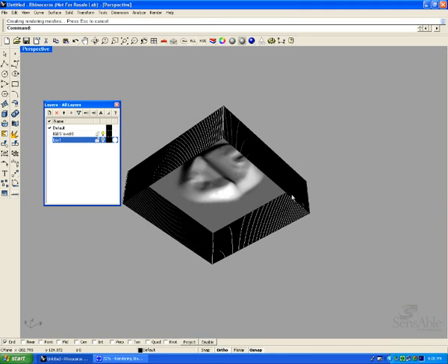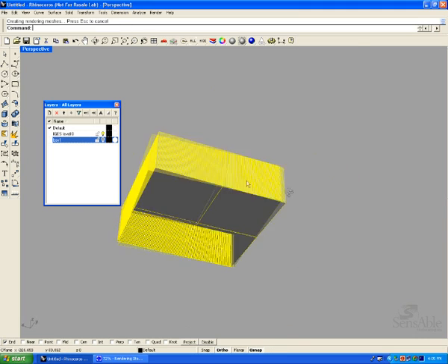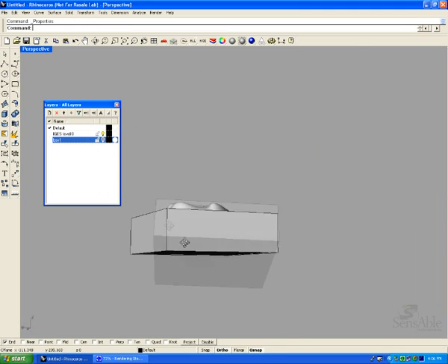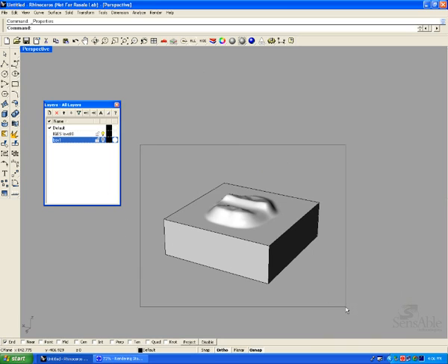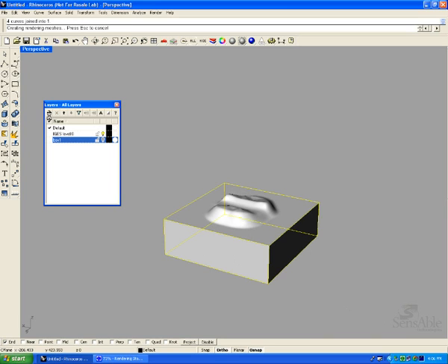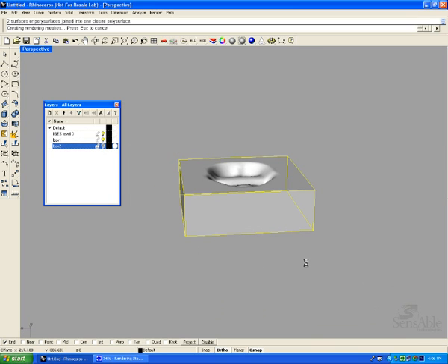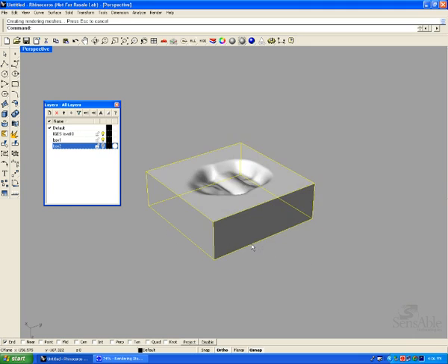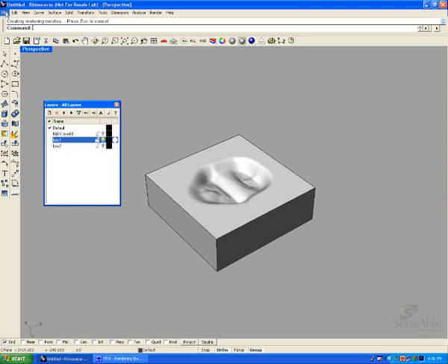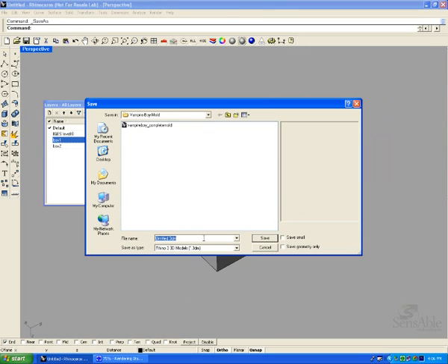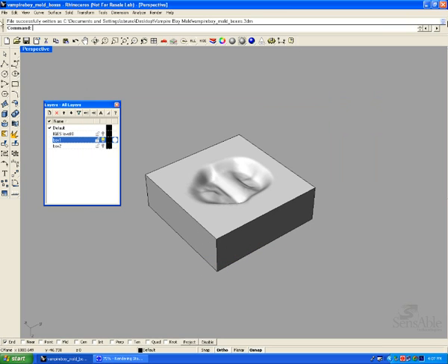mold. I'll copy and paste the parting surface so I get a duplicate, and then I create a new insert block on the opposite side, so I have the two parts that combine together into a complete mold for the tooling to be manufactured. Now you can see that there is no void in these insert blocks yet. At this point, now that I have my two insert blocks with no void, I can import the positive piece of the part that I want to be molded.